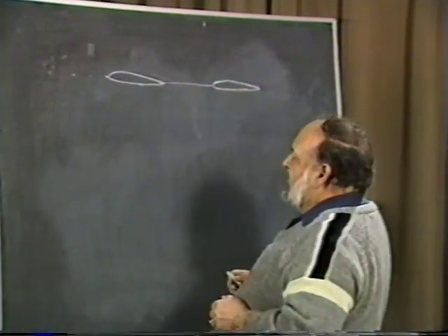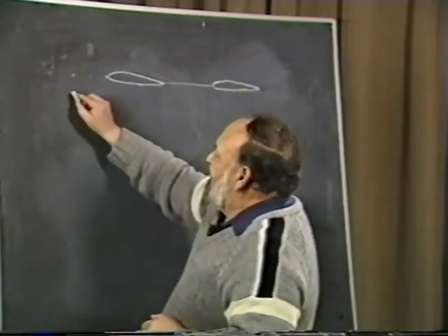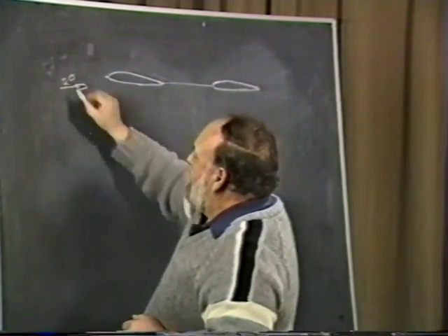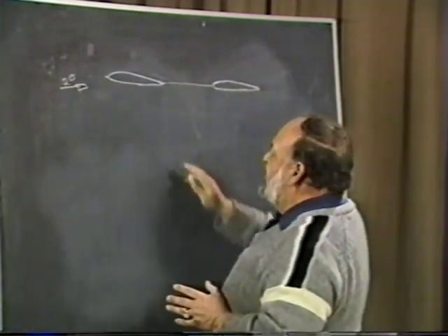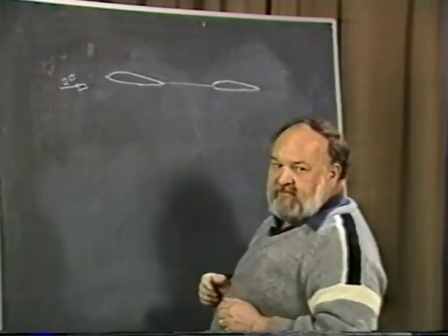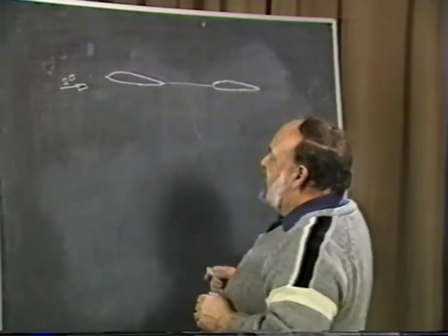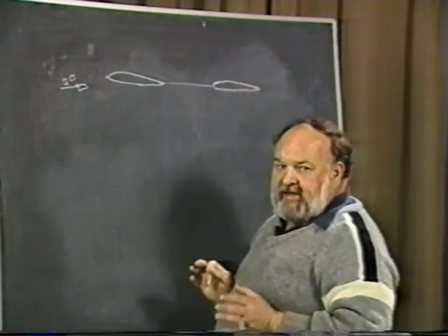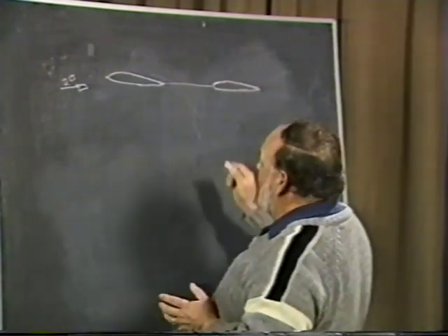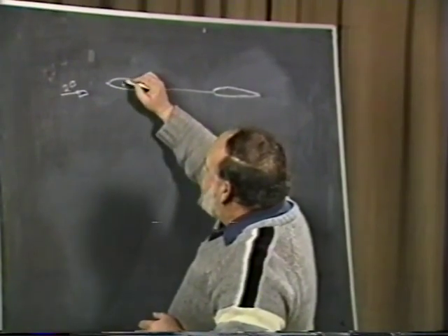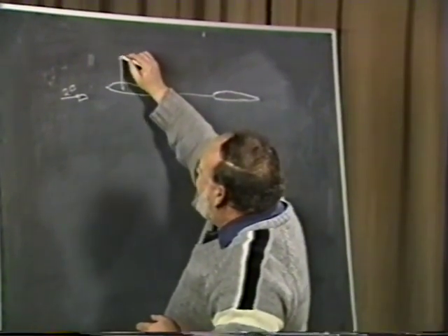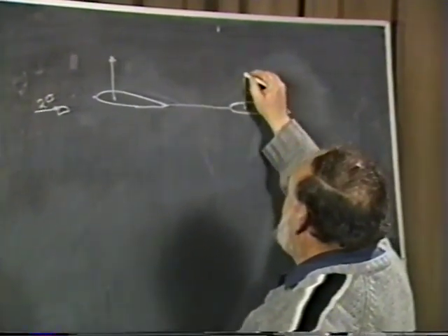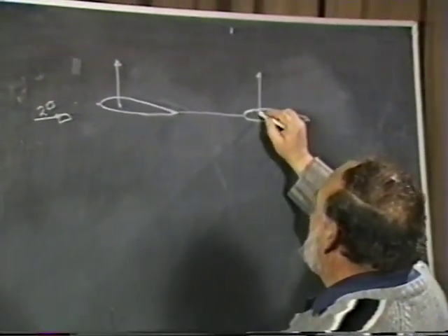at the same angle of attack. If we were flying along at a 2-degree angle of attack right here, and in this case, let's forget the downwash off the front surface on the back one, just to keep everything simple. So we could say the back one, sitting at the same incidence, has the identical angle of attack. Well, in that case, the lift generated from this wing at quarter chord would be identical to what the back one is lifting. Both would be the same.